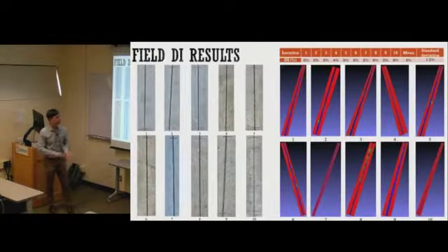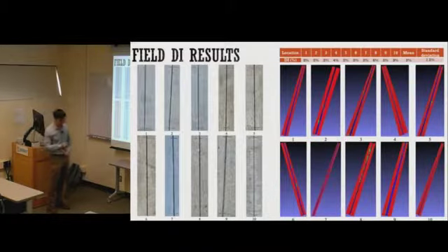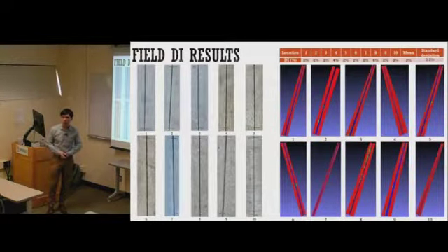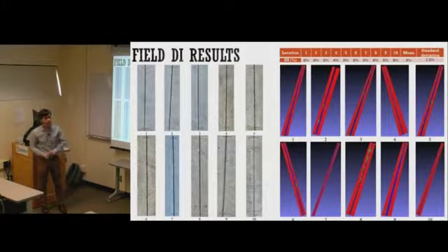I went to different sites, 10 different sites, 10 different locations, 10 different saw cuts, from I think 2 or 3 projects in Champaign and Urbana. I quantified them using this computer vision technique. And what I found is they vary, of course, but they vary from 2 to 6%, with the mean of 3% and the standard deviation of 1.2%. So let's say that if I take 3% as the acceptable damage index, then what should I do next?